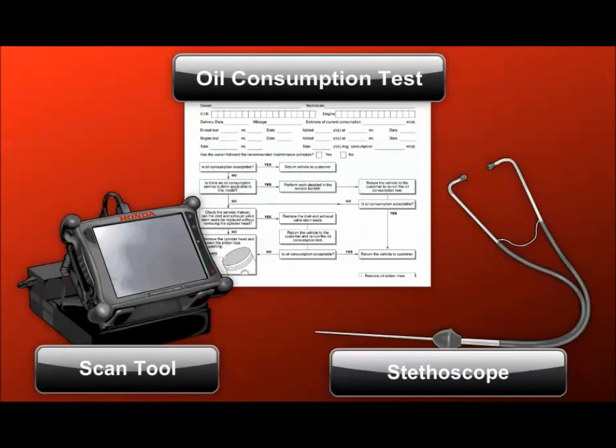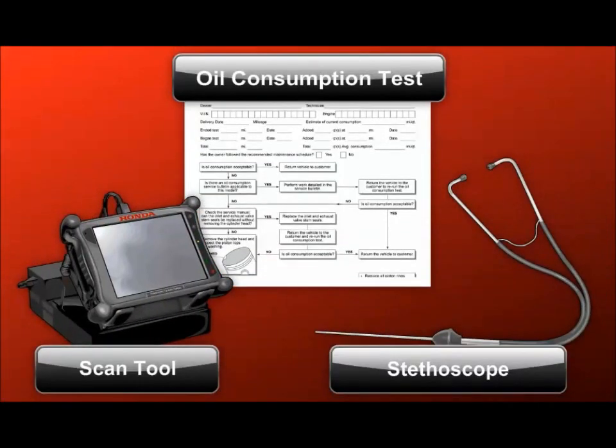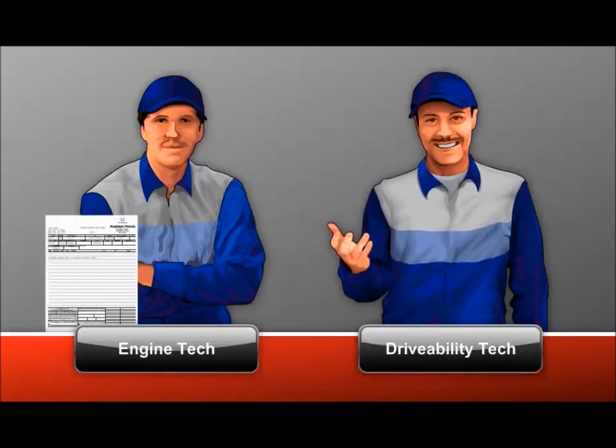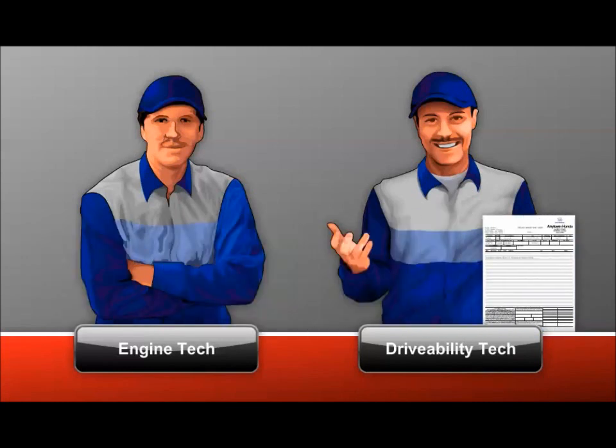This module provides several checks to help separate drivability problems from engine mechanical problems, but not all faults can be divided using these checks. Technicians who cannot troubleshoot both systems should check over the engine mechanical system, and if they find no mechanical fault, pass the car on to a knowledgeable drivability technician who can correctly evaluate the fuel system.